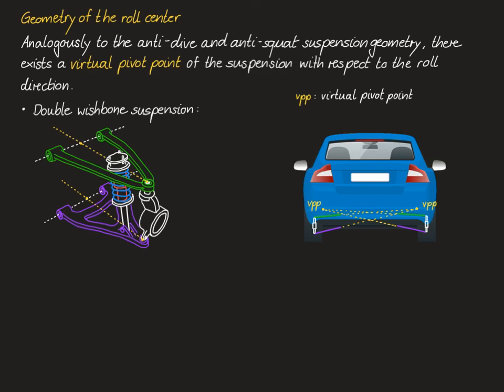Instead, what is fixed is only the contact patch between the corresponding tire and the road. In our assumptions, this contact patch is represented by the midpoint of the contact patch for each of the tires. So the assumption is that the wheels are fixed at these 2 points, but otherwise the wheels can tilt to the outside or the inside, which is called the camber direction.